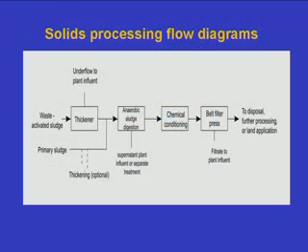Okay, now we will see what are the processes we usually use in wastewater treatment plants. So, if the waste activated sludge is coming from an activated sludge process, first we go for a thickener. Thickener we have seen in detail, how to design a thickener. The secondary sedimentation tank itself will be acting as a thickener. Here the sludge from the activated sludge process as well as the sludge from the primary sedimentation tank can come and the thickening can take place.